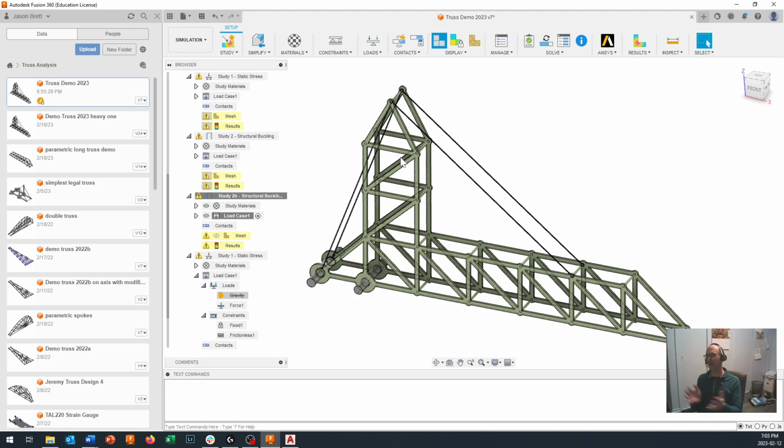You will still have to build a model and test it to validate your results. Okay, simulation is good, but it can provide bad results sometimes unless you test your model and are very sure that you know what's going on. So create a truss that you think is going to be good, that you think is going to be strong. Create a model, record where it says the model is going to fail, and then come in and build and test that truss.